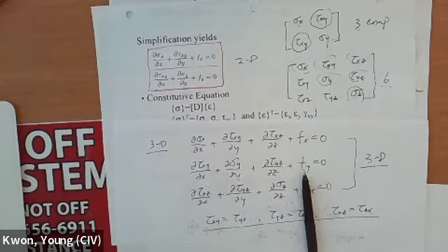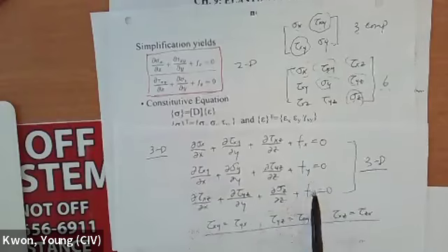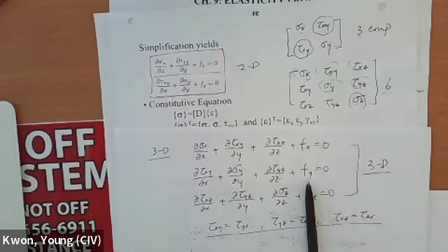That is much more difficult to solve. That's why people prefer the mechanics of materials structural element concept as long as it provides the right solution. But for some examples we talk about today, unfortunately, they cannot capture the solution. Then you have to solve the problem using theory of elasticity, the so-called continuum element.